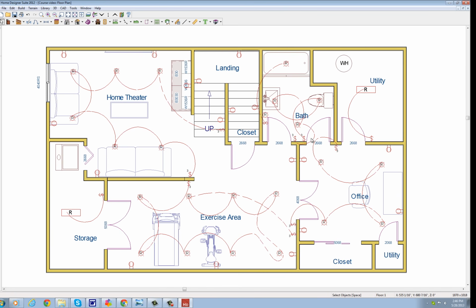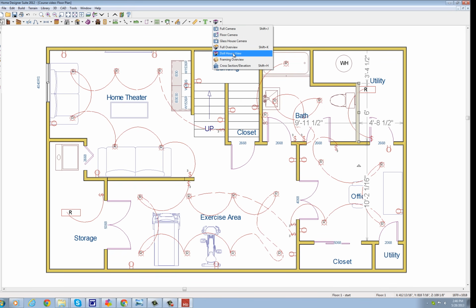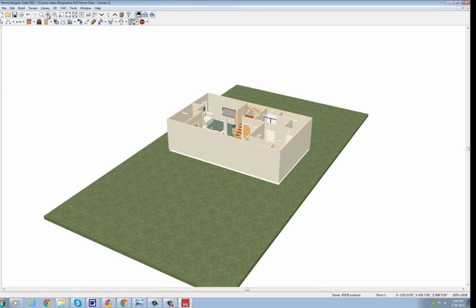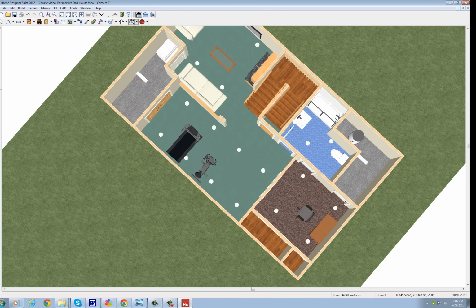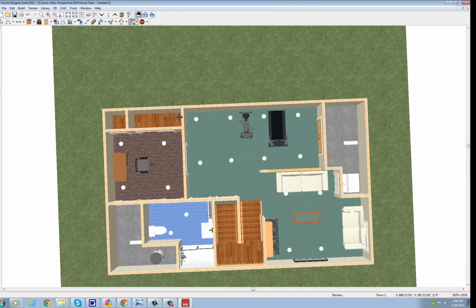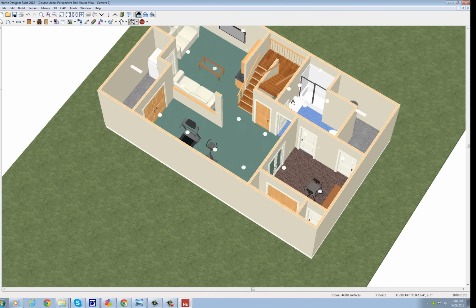If you didn't like what you saw in 3D there, if you thought the bathroom should have been bigger, you can go in here and just as simple as go into the Select Objects icon, left clicking it. Let's say we wanted the bathroom to be wider. We can move this door down by clicking it and dragging it down the wall. We can grab this bathroom wall here and drag it down 3 or 4 feet. Boom. Now look how big our bathroom is. Go back to the dollhouse view. Zoom in on that once or twice, and take a look down in there now. And now look how big our bathroom is. We slid this wall back just that easy, just to make a bigger bathroom. Whatever you want to do, you can do with this program.